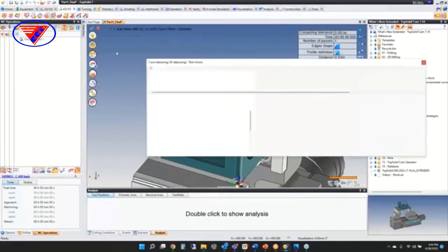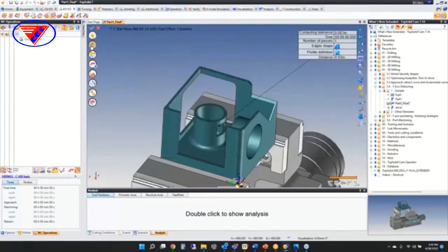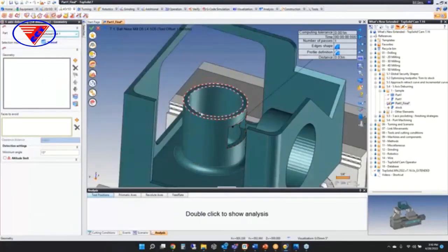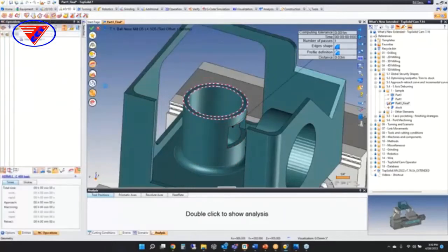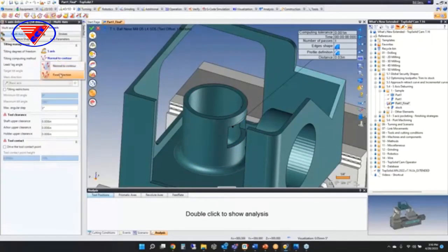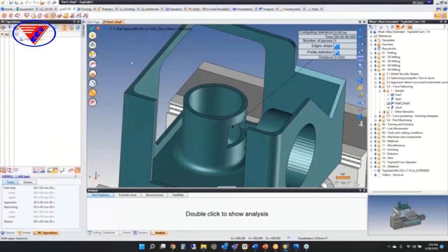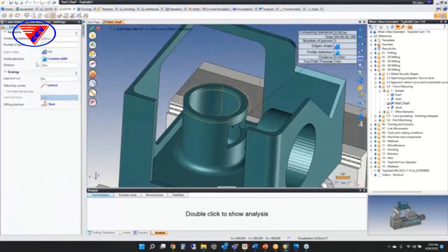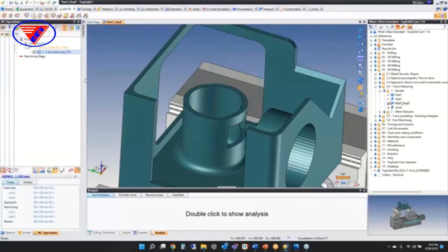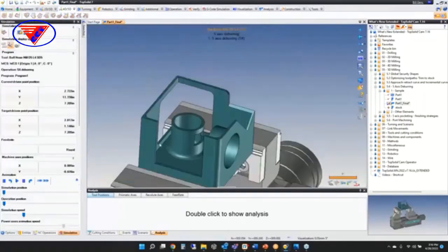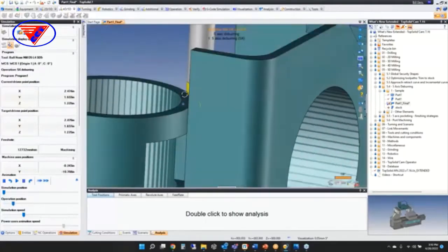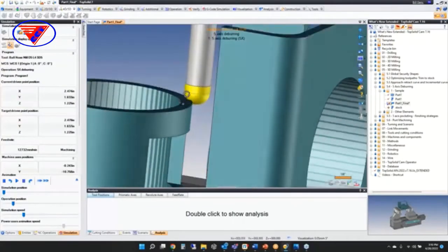So I'm going to go to deburring. I'm going to pick a tool. It's going to be my ball nose end mill for now. That's fine. We're going to select some geometry, and we're going to keep it nice and simple right now. I'm going to select this one and this one. We're going to go to multi-axis, and I'm going to say fixed direction, and that's it. I should point out, I'm just using the default values. We're putting a 30 thousandths edge break on the part. So, if I run that simulation, this is that first one we saw where it comes in and it literally just breaks the edge, right?